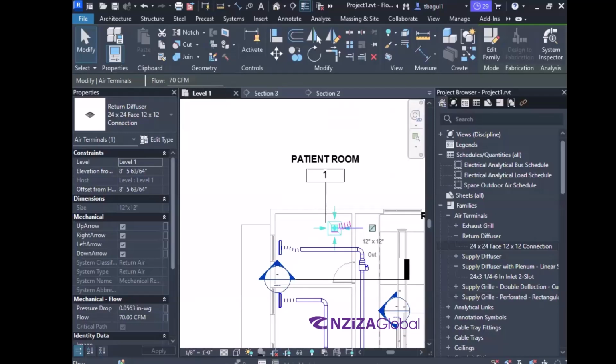That is fine, but we don't want that other 10 CFM to come in and add to our loads that much. Make sense? Positive pressurization. I know it is not required return. So not required means you can either have it positive or negative. But if there is a restroom right next to it, that restroom needs to be negative. That would make the patient room positive pressurized.